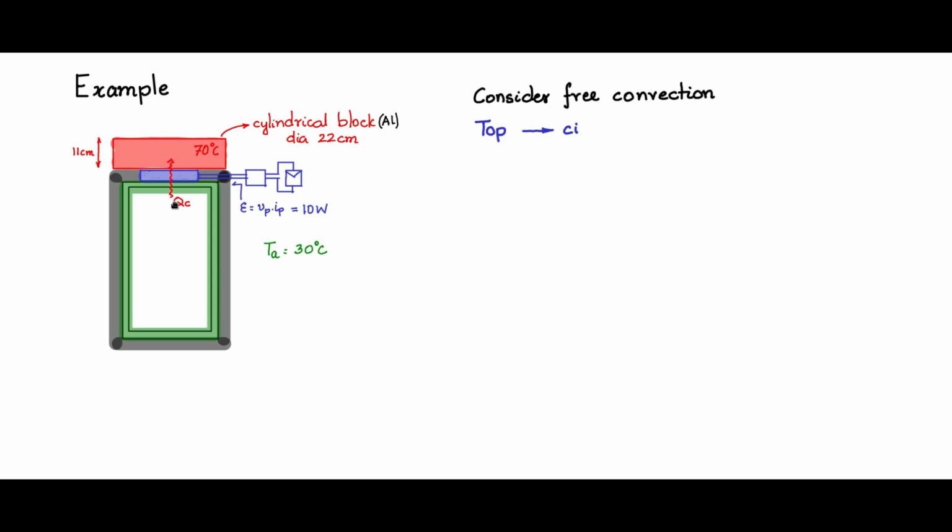The heat can transact with the external ambient only through this Peltier element, because everything else is covered up with thermocol. Once it has gone into the hot body, which is the heat sink, it can go out into the ambient only through the top and through the sides. So let us find out how much heat is going out from the top and the sides. Then we will have an idea of how much QC is going out through the Peltier element.